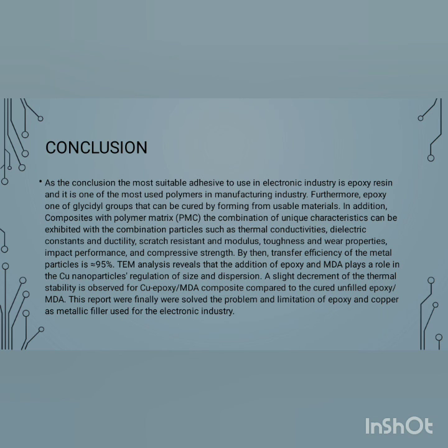The TEM analysis reveals that the addition of the epoxy and MDA plays the role of regulating the size and dispersion of the Cu nanoparticles. A slight decrement of the thermal stability is observed for the Cu epoxy MDA composite compared to pure unfilled epoxy MDA. This report solved the problem and the limitation of epoxy and copper as a metallic filler used for the electronics industry.